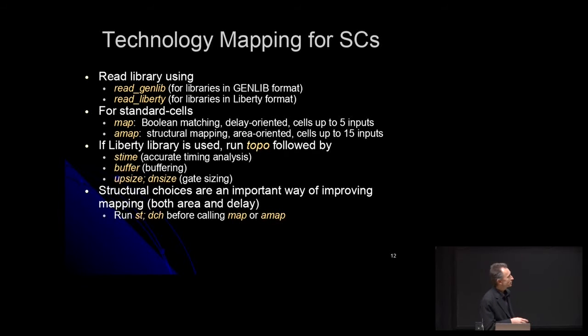You can read either a simplified gate representation in genlib format, or you can use the Synopsys Liberty format, and it will extract delay and area parameters from that format, and even wire delay models and other things as needed. And all those mappers will be able to apply mapping.